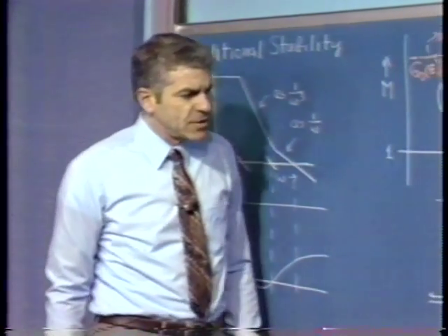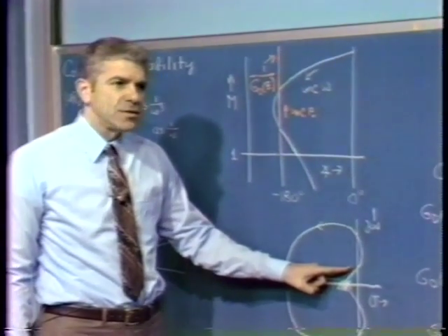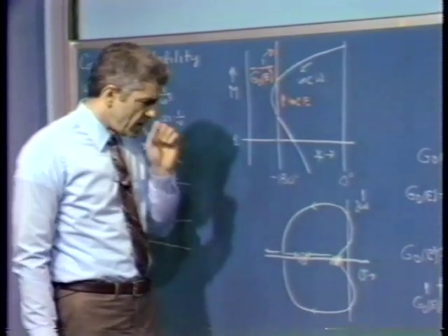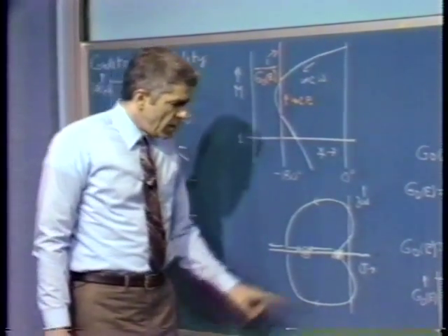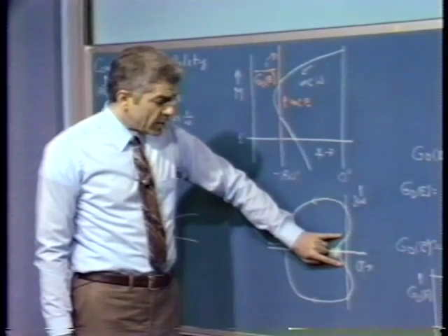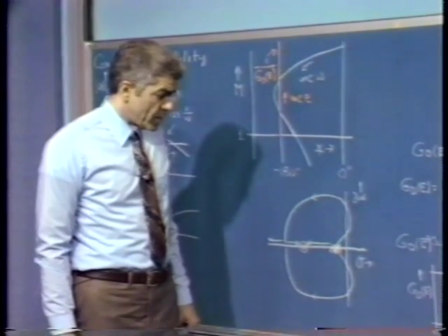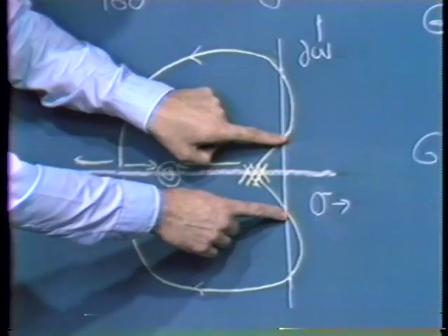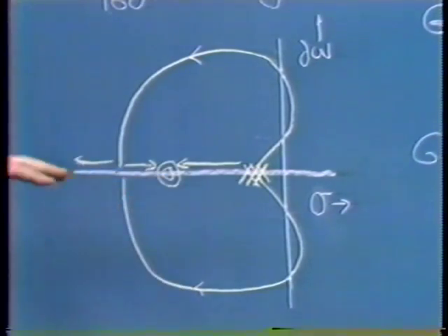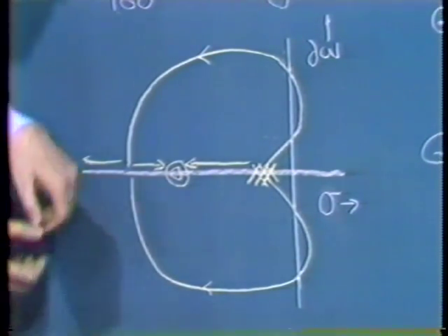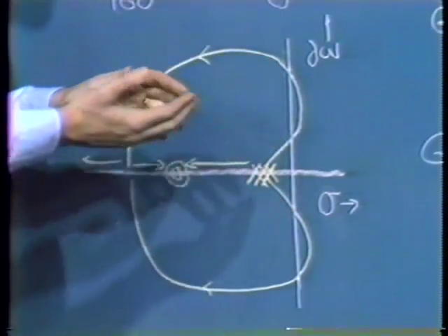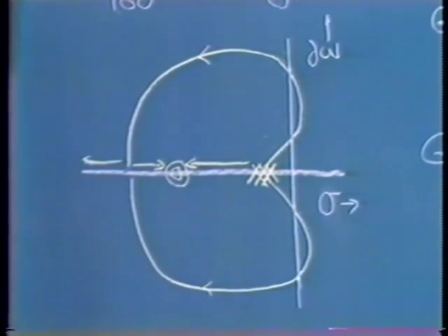Again, we can make the same exact kind of argument, and I think it's worth comparing these cases, in a root locus presentation. Suppose, for example, we had the correct amplitude so that when we considered the gain of the nonlinearity, the describing function for the nonlinearity, our pair of closed loop poles was precisely on the imaginary axis. If we assume a slight increase in that amplitude, the magnitude of the describing function decreases. We move back in the left half plane. The system's stable. The amplitude shrinks back to its original value, and so forth.